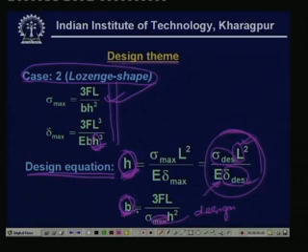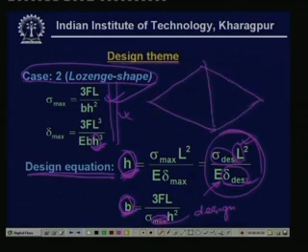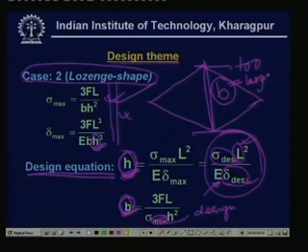See the b value what you obtained, considering this aspect, with these values of sigma, deflection and L, can be a too large dimension. It can be too large a dimension to accommodate in a machine assembly.